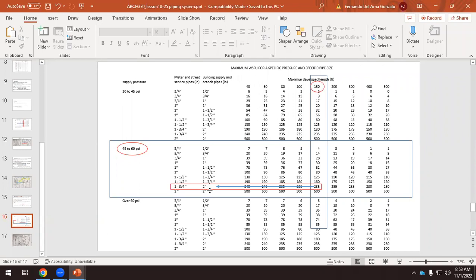Does it make sense? Yeah, I have decided that this is 1 3/4. I will have another one with 1 3/4. So if I connect at least 4 1 3/4 minimum, this should be 2 inches. Okay, so that should be 2 inches. And then this vertical one would be 2 inches. It should be 1 3/4. This would be 1 3/4. This branch that goes to the flat restaurant. This would be 1 3/4. It would be 1 3/4, and the vertical pipe would be 1 3/4.